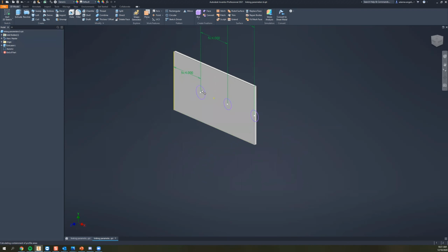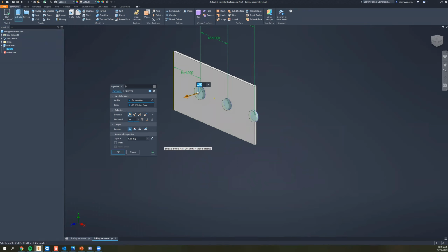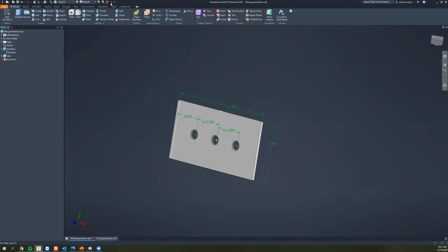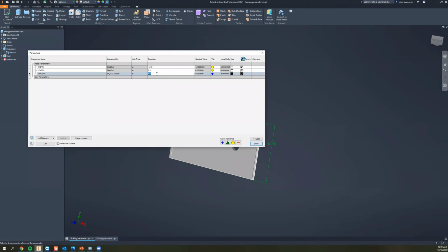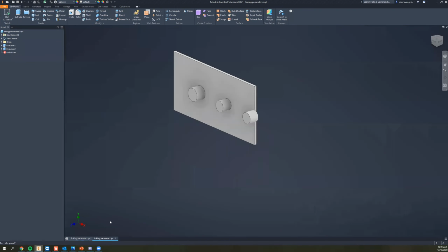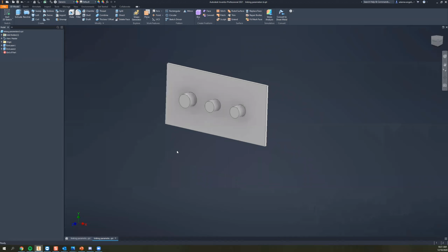And so now I could go ahead and extrude these lengths over here. Call that 1 inch. I'm going to click OK. Come back to the original part, change the spacing to something more palatable, like 3 inches. Done. Throw an update over here. And we could throw an update here as well. And that should update the spacing accordingly with these two, right? At this point now, I could go into an assembly and I have a lot of confidence that these two parts are going to be able to interface pretty well so far, right?